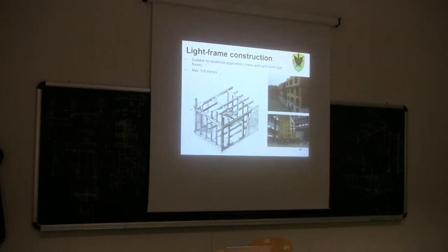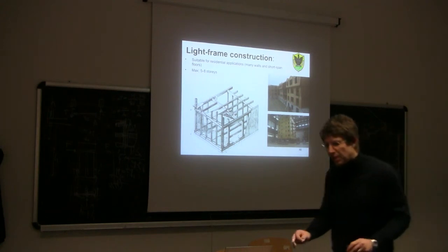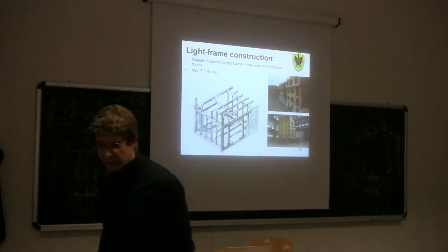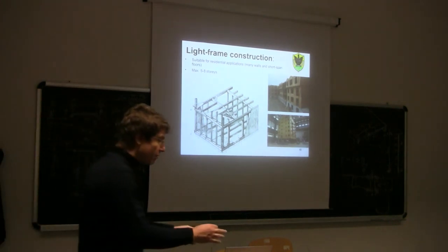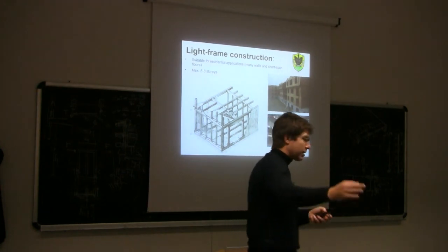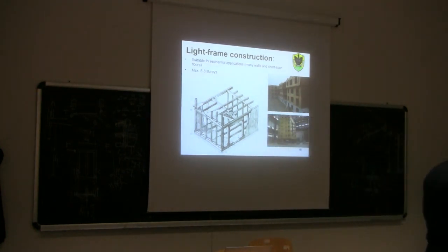I'm going to show you shortly 6-story buildings made with this kind of system, constructed in a situation similar to L'Aquila, in Wellington, New Zealand, which is the capital of New Zealand, and where the city is built right on the fault line, more or less like here. Even worse, I would say, because here the fault line is not really in the center of the city. And you will see that there were lots of problems. You have to use lots of wood, so it's not so simple. So I would say, in L'Aquila, max 4 to 5 stories in a high seismic region.